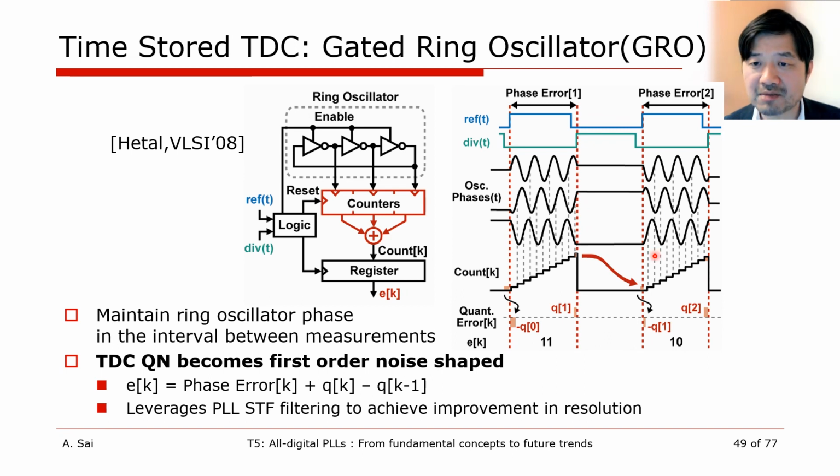This is very effective in reducing the quantization noise because it is driven to high frequency by the noise shaping, and after that the ADPLL low-pass filter can furthermore suppress the quantization noise.